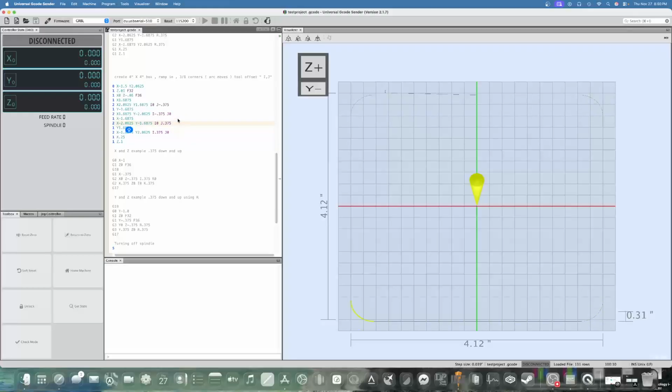Come down here to the other side, we're again bending it on the y-axis, but this time we're pointing up, pointing towards the positive. So you notice here, I is 0 because we're on the y-axis bending, or I guess curving. And you notice I now have a positive 375. The 375 is the actual corner radius, and positive because of the direction we want.